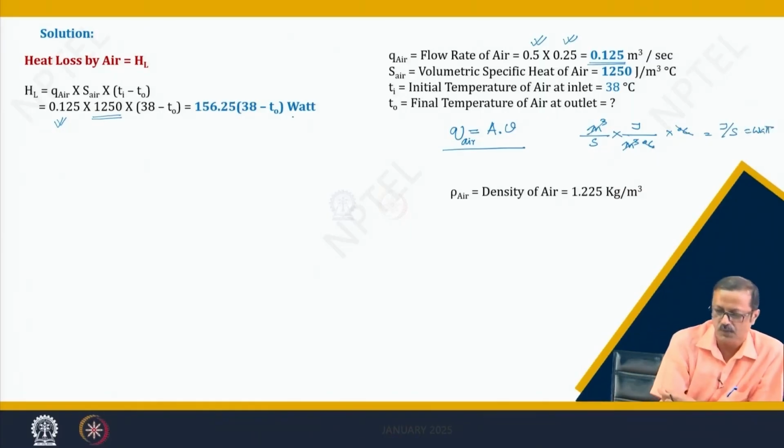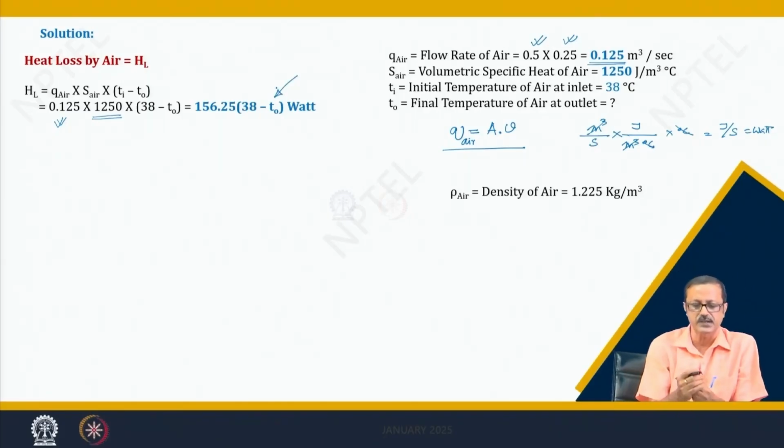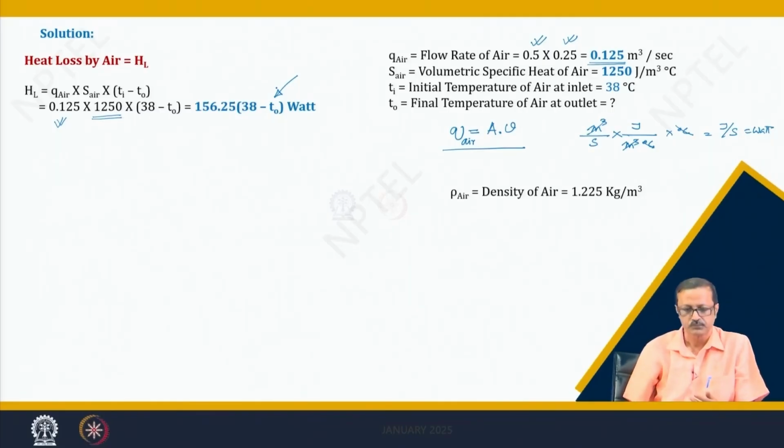So, very similarly I got the value in joule per second. But here this term is still yet to be found out, that is, how much is your treated air temperature. I have taken the air from the inlet as 38 degree; what will it be after this passive cooling, that is the temperature I have to find out.